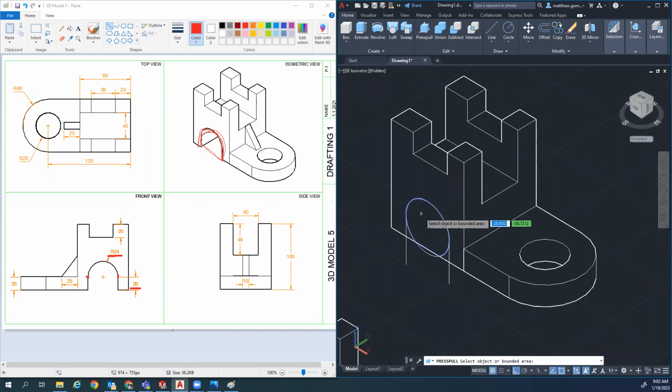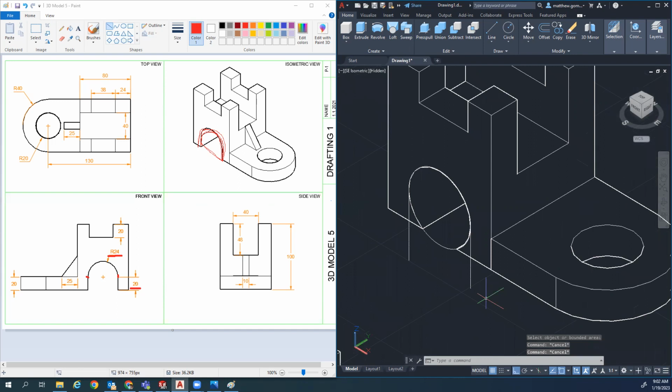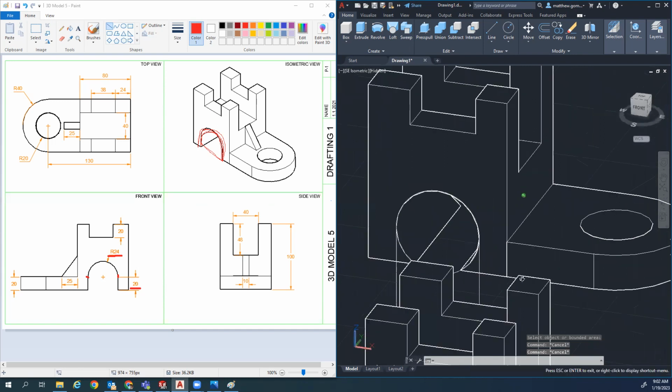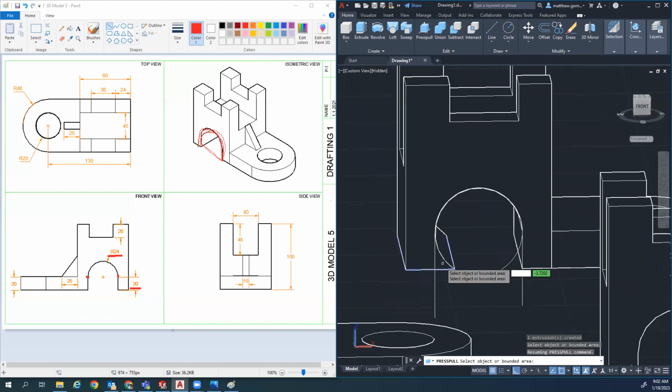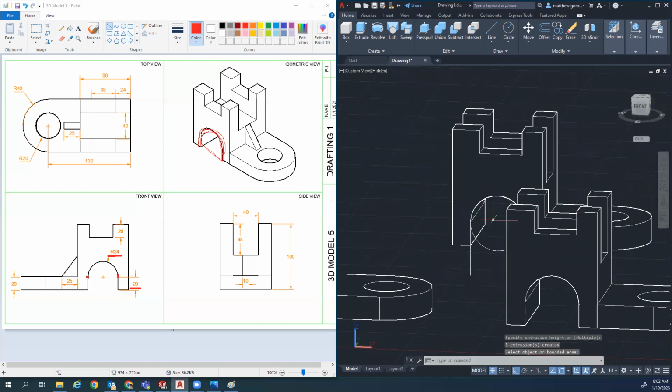Because when I press pull this circle face, it cuts out the circle, but you're left with these 2 little triangle things. If I orbit around, that doesn't look right. I still need to press pull this little corner. So I get right there and press that back. And now that looks correct over there. And then I press pull this face back as well. So there's 3 press pulls you have to do with that little shape.